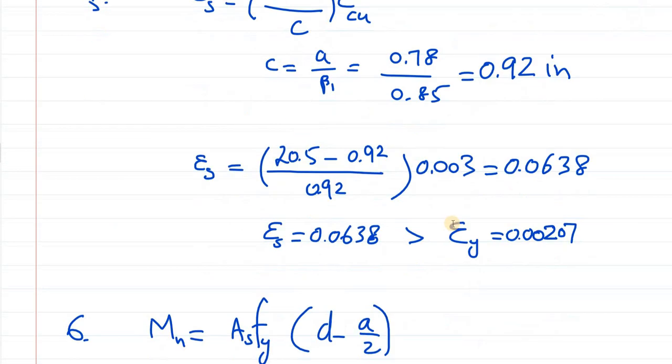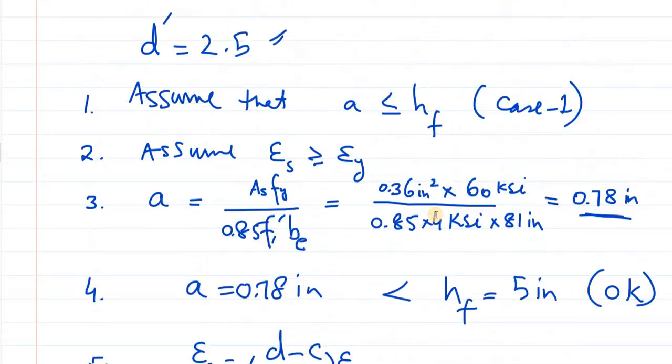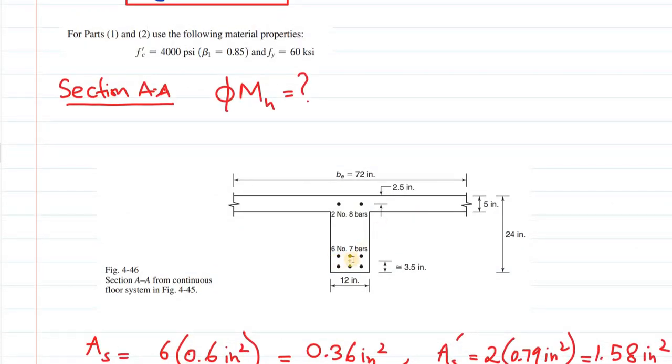So if you wanted to incorporate its effect in the calculation of bending moment, you could have included it by considering that now you would have two tensile forces, one acting at the level of d, and the other acting at the level of d prime. Both are tensile. If you just consider the strain diagram, it would be probably looking like this. Let me show you. This is how the strain diagram would look like.